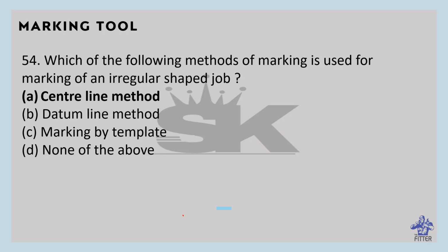So there are many methods for marking. The first one is the centerline method. This method is used on odd shaped, irregular jobs. An imaginary line is drawn in such jobs for marking, and other lines are drawn on its basis. And the second one is marking by template.